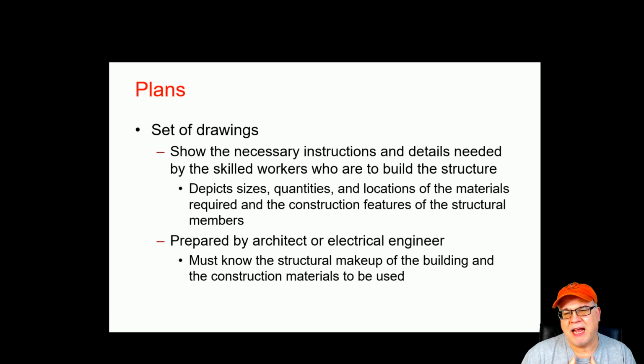Now, as an electrician, I've laid out many a house, and all I had was the layout of the house. The owners want to know where you're going to put things, unless, of course, you're doing what we call a spec home. And that means you're just simply laying out the receptacles and everything to specification. That'd be the 6-foot, 12-foot rules that we see in 210.52 of the National Electrical Code. And then you're just putting them at a point so that no point along a wall line is more than 6 feet from a receptacle. Okay, so all these types of things are part of the design, and whether or not they're already on the drawings or you have to put them on there, again, there are things that you need to understand.